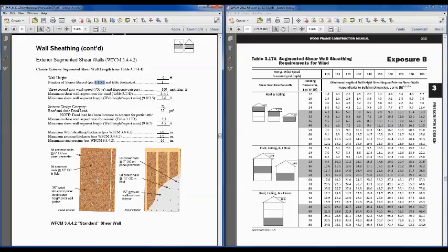In this particular case, we've got a partial attic, and so instead of doing a conservative approach and assuming an additional story, what we can do when we get to the seismic design is increase our dead loads. And so we're going to assume 1 story instead of 2, and then we're going to increase our dead loads per some of the footnotes. And so we'll point those out when we get there.